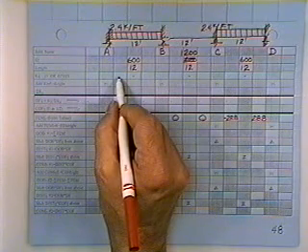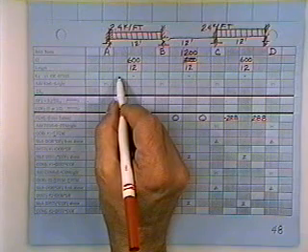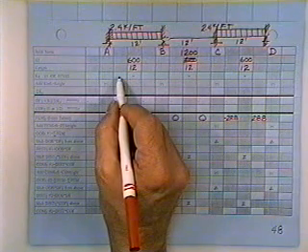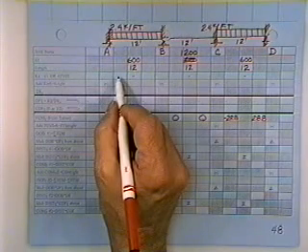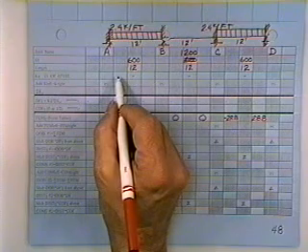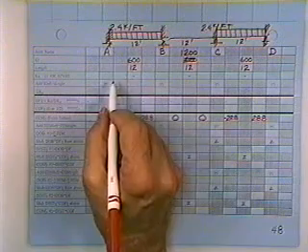There's a pin there, I admit, but the member goes on. The member doesn't stop at a pin. K sub ij is 3EI over L if the other end of the member is pinned and quits and there's nothing else out there. That would probably be better wording.